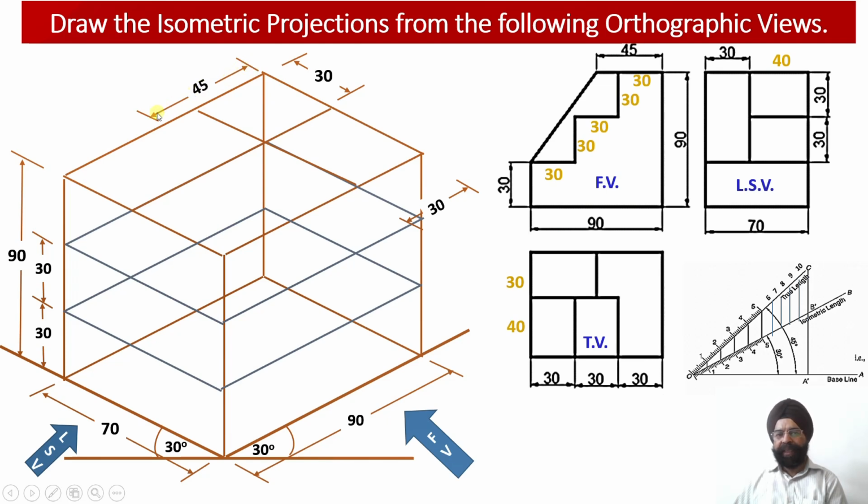The moment I mark this distance, now another isometric line will be constructed which will be parallel to the x-axis over here. So this is my x-axis. This isometric line will be drawn on this top web. Now I can see that this is a web which is an angled web over here, and it turns towards the left side on the top face. So this gives me the construction of the top angled web over here, right? So this is the construction.